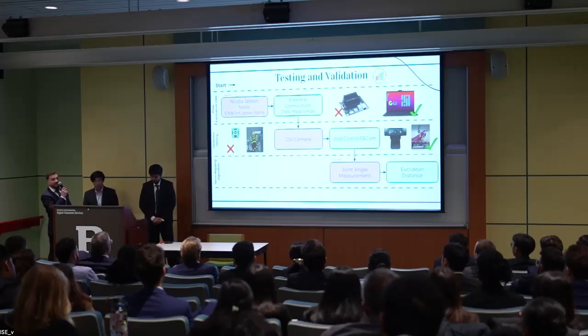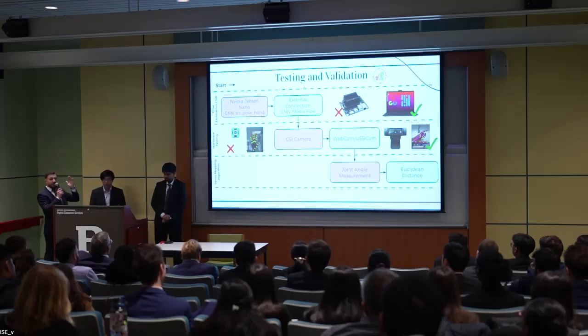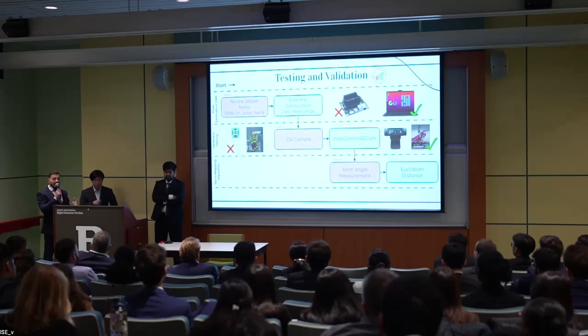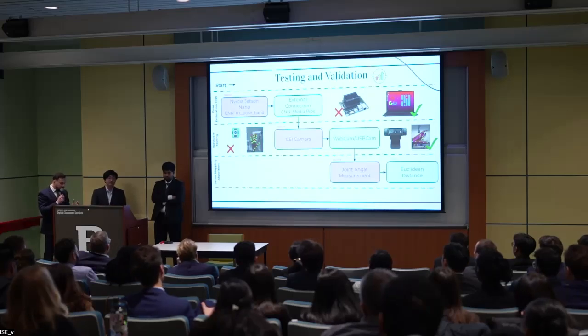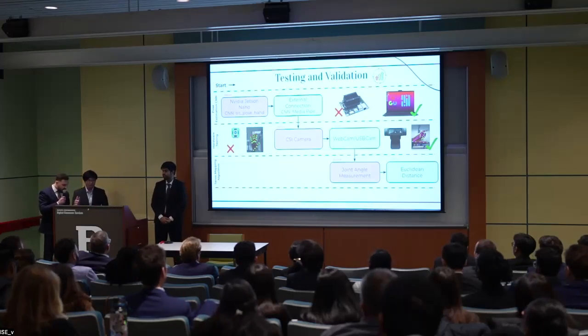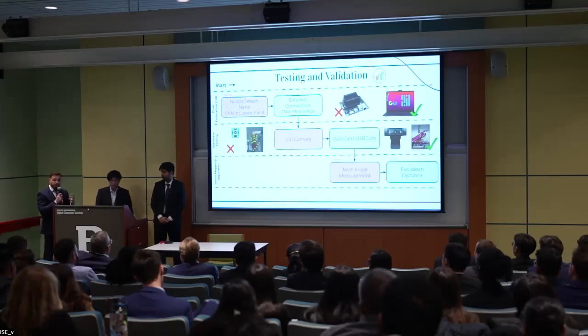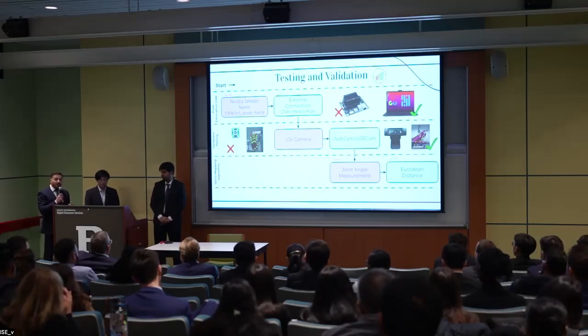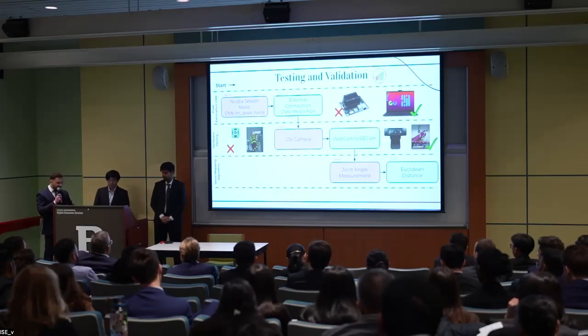Now our testing and validation, starting with the first step, the pose estimation CNN. Before, we were using a Jetson Nano with the TRT Pose hand CNN model, and this setup was slow and faced memory issues. So we switched to an external connection with the MediaPipe hand tracking model on our laptops. That provides a smoother and more fluid model for tracking the hand.